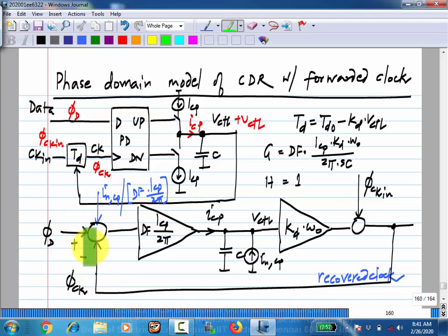On the other hand, you also use this recovered clock in the rest of the signal processing, maybe to retransmit. These things become a lot more important when you don't have the forwarded clock. When you have a clock from the other side, you could also pass it on to the following stages. But when you don't have a forwarded clock, you are regenerating from that, so the jitter in the output clock becomes important.